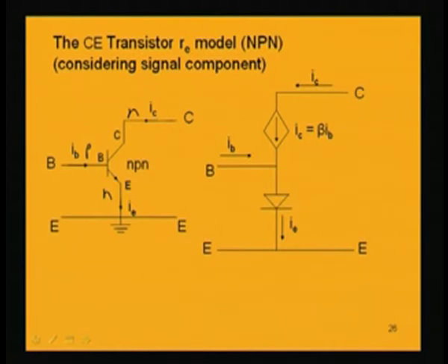current source in the collector which is nothing but beta times IB. So, IC can be expressed as beta times IB, and so in the collector to emitter output circuit, there will be a dependent current source, beta times IB. But one thing to be noted here is the point of joining between the input and output circuits.